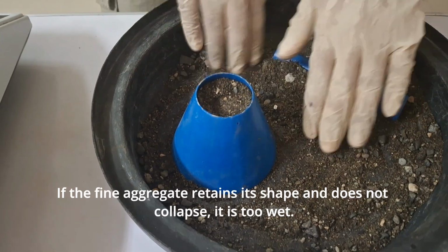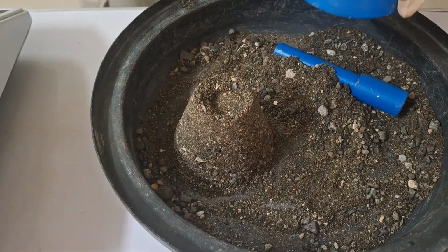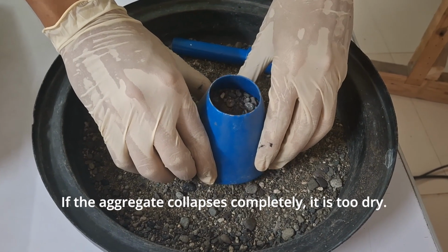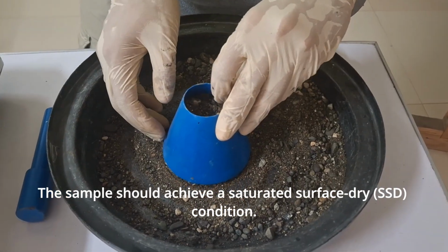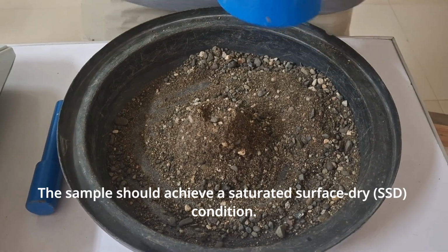Carefully lift the mold. If the fine aggregate retains its shape and does not collapse, it is too wet. But if the aggregate collapses completely, it is too dry. Adjust the moisture content as necessary by drying or adding water. The sample should achieve a saturated surface dry or SSD condition.